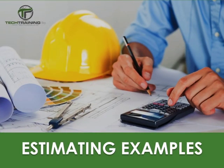So as we go through these estimates, keep in mind again, they are conceptual. They would be done in the conceptual phase of the project. And also keep in mind that the accuracy of a conceptual estimate is minimal. It is typically plus or minus about 25%. They are designed to simply give an owner a very general idea of the cost. And if they agree or disagree with that cost, they can make their go or no-go decision on the project.